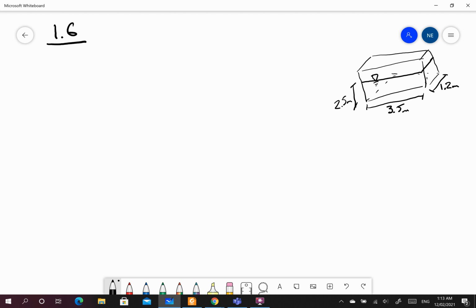Alright. So what have I got? What do I know straight away? Well, the RD of my kerosene is 0.8, and I have a weight of the tank, so my W tank is 4 kilonewtons. Heavy tank. Alright, so if this is my RD, I know that my rho is 800 kilograms per meter cubed, timesing it by 1,000, the density of water.